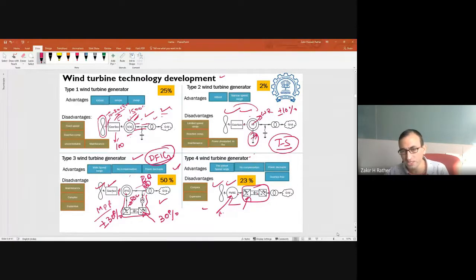So what is happening with this type 4? It is clear that it is not going to provide inertia to the grid. It cannot provide inertia to the system, the reason being that it is not synchronized to the grid. The machine is not magnetically locked to the grid. If you see type 3, you may still say that the stator is connected directly to the grid, though the rotor is connected through the back-to-back converter.